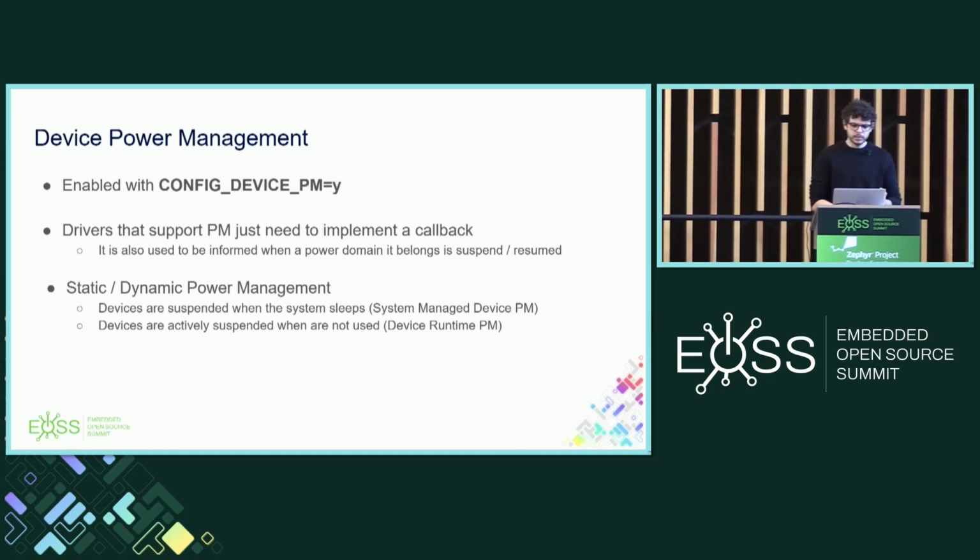I have mentioned it, but on Zephyr we have these two methods to do device power management: static and dynamic. Static is also called system managed power management. It's the one where when the system goes idle, we suspend devices, and when the system wakes up, we resume them. Dynamic or runtime power management, which is the nomenclature that is more used, is the capability of suspending or resuming devices automatically according to their usage, and it does not depend on the system power management. It does not depend on the system being idle to happen.